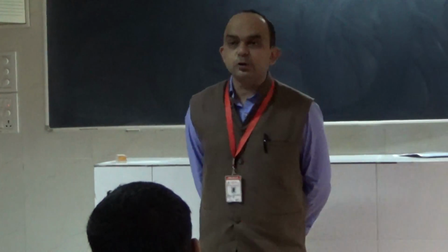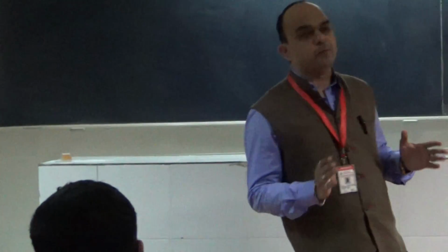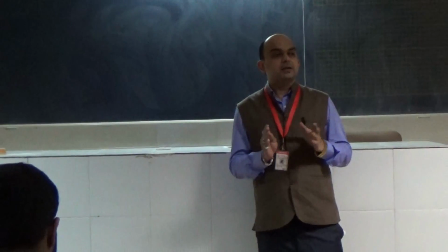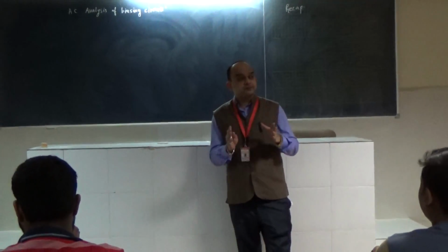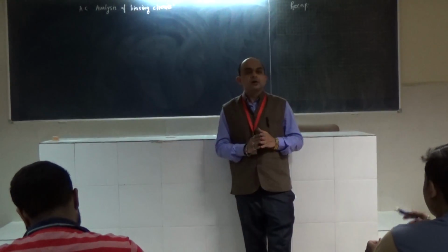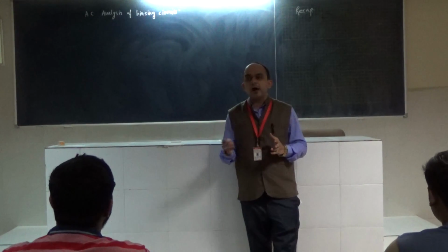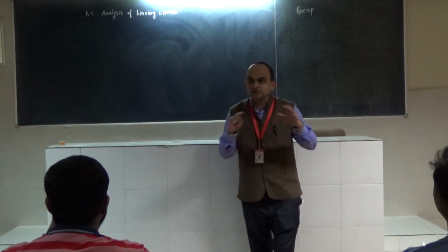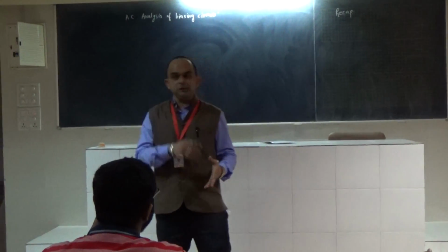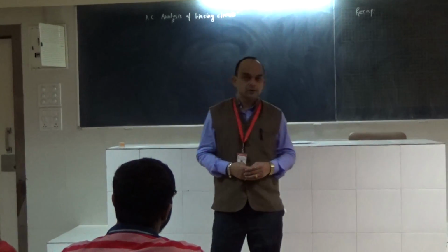What basically we are doing in the DC analysis is finding out the quiescent point. What do you mean by quiescent point? Where the amplifier gives the faithful amplification. What do you mean by faithful amplification? The shape of the input waveform is preserved after amplification. There is no saturation, there is only faithful amplification. If a sinusoidal is given, in the output you will get a sinusoidal.